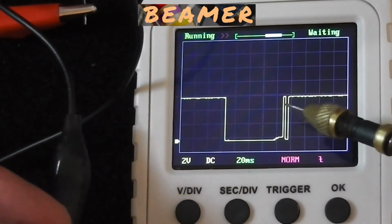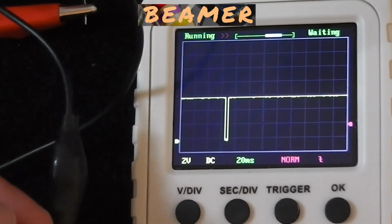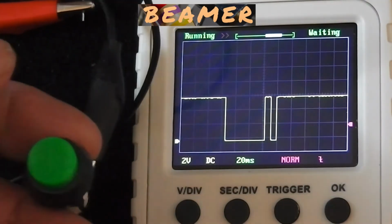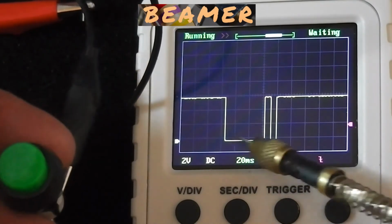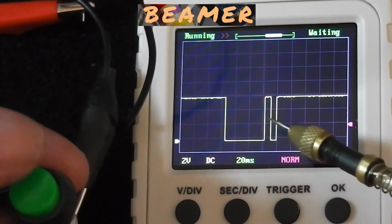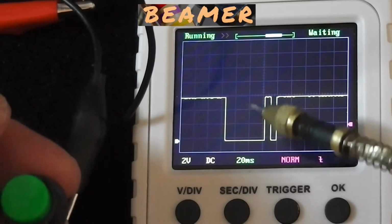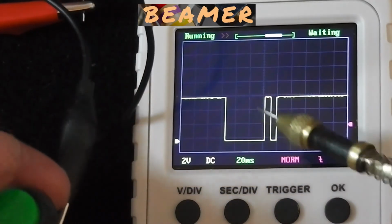I don't know whether you can see that again on the rising edge. You've got a double switching action there. There you are, and you can see what's going on here quite clearly, again on the rising edge. So this is when the switch is being lifted off. It's producing a bit of, I suppose you could describe it as oscillation, but the switch contact is not being made completely purely.